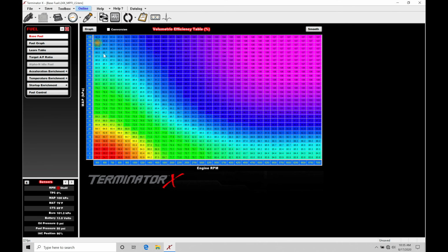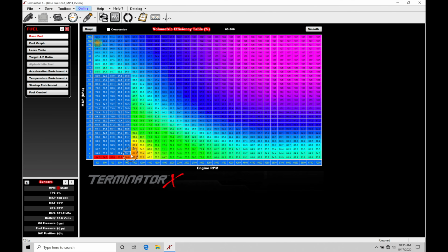If I fired up my engine, I'm going to find that it's going to idle anywhere between 500 to, let's say, 1,000 RPM. I'm going to be in this range, and I'm typically going to be anywhere from 70 to around 30 kPa in my engine vacuum. Depending on the size camshaft that I'm running, it's going to vary a bit. So let's assume we're in this range right here. So this is going to be where we would want to make our editing change.